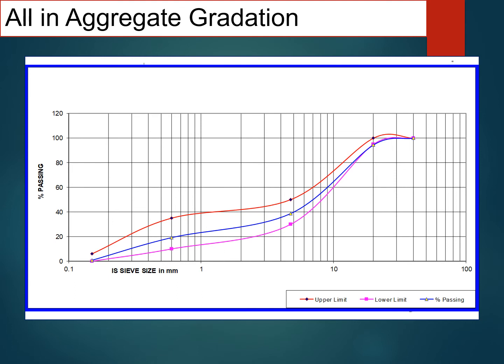Once the theoretical grading is done, the required quantity of aggregates needs to be taken and then sieved to check whether the percentage passing is physically, or actually, being achieved or not.